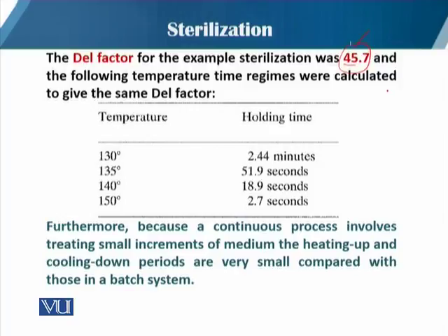In this table you can see the holding time required at 130 degrees Celsius, and if we raise the temperature to 135 degrees Celsius, the holding time reduces from 2.44 minutes to approximately 52 seconds. So just by a rise of 5 degrees Celsius, there is a decrease in holding time.